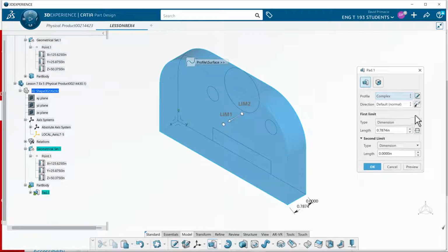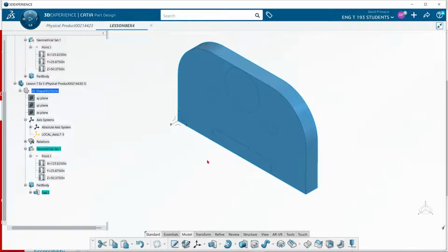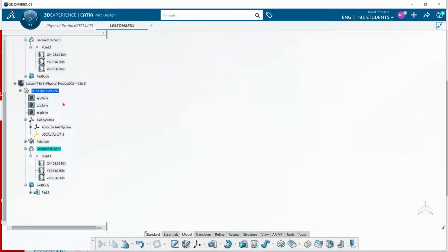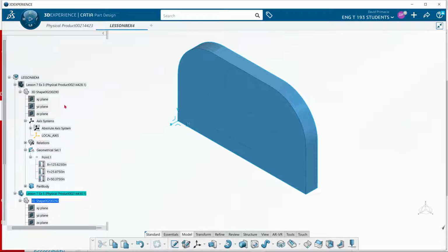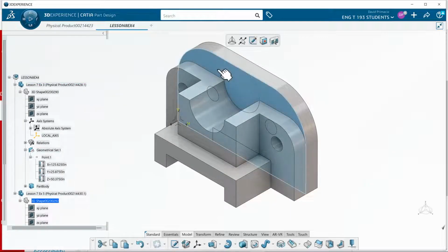And I'm going to reverse the direction, and I believe it's a 1/2 inch. And the reason why I'm reversing the direction is this face has to touch that part. So that's a datum, and the face that's touching is the datum.